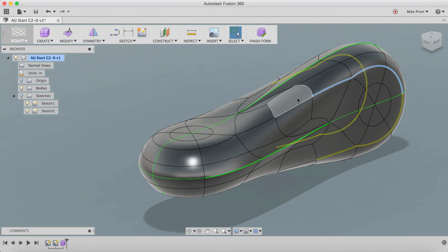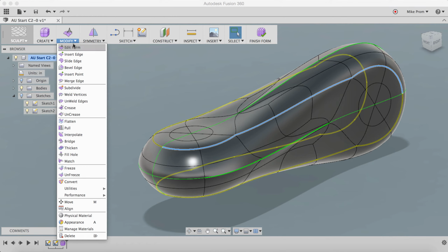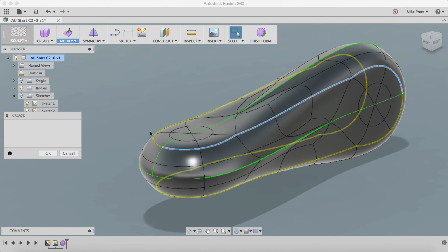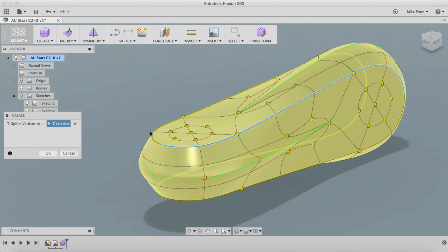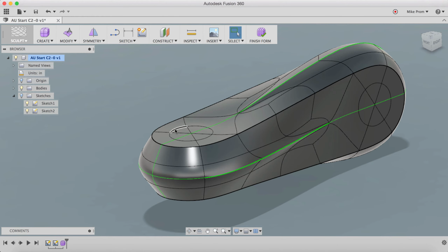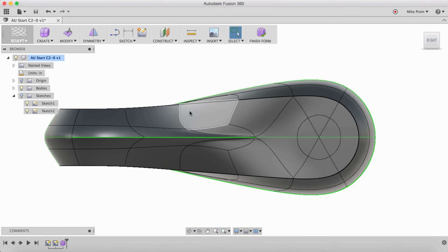Now that I've creased one side or edge, I'm going to crease another section. Notice when I crease this and improve the profile loops all the way around, that there's a nice crisp edge where the circle blends into the line. Just like before, I have a nice hard edge. In order to emphasize this, I can manipulate my model by grabbing points, dragging them around, and exploring.